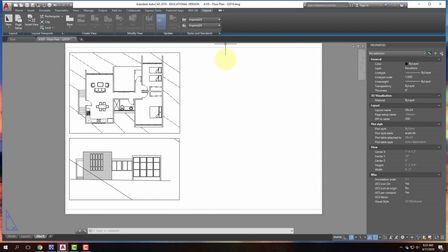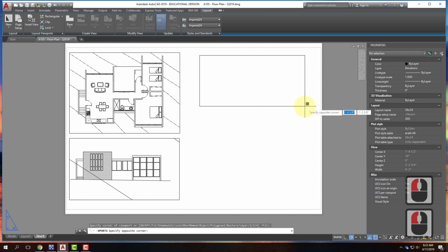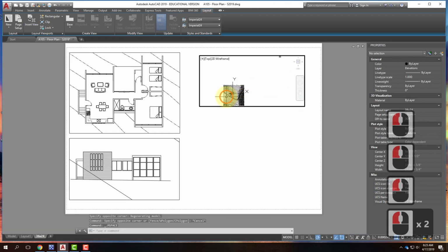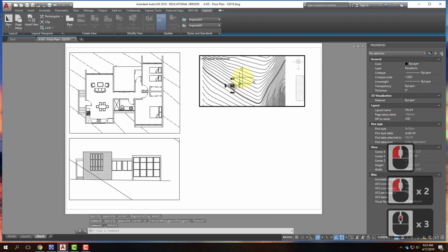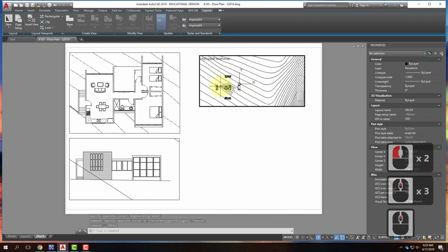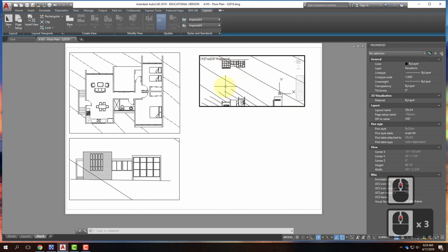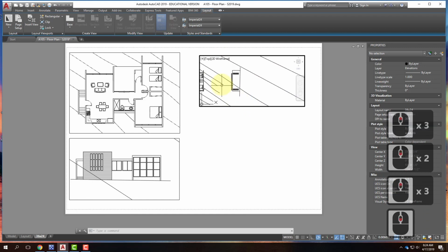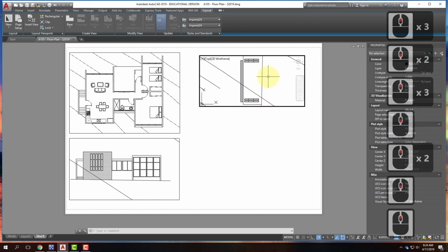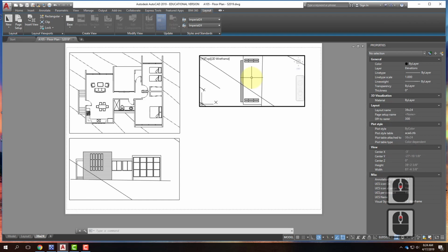I'm going to lay them out on the right side here. I'll come back in the layout ribbon to my rectangular viewport. I'm going to create another viewport. I'll double click and I'll zoom in. For me, it's always easier to get part of your drawing, basically kind of center your drawing in the viewport first, getting it close to scale and then adjusting the scale.